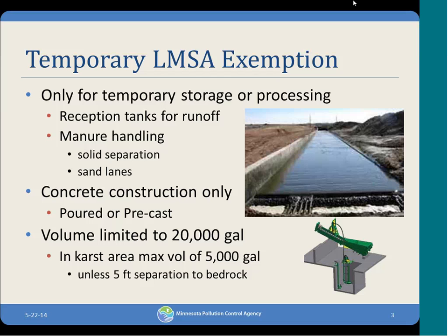Okay. Any other questions for Allie right now? All right, so one question is, how many days after the floor pour can it be walked on to inspect? Next day? Yeah, you can get on it the next day. You want to see how it's curing. If you see that there's kind of a slick on top, use your best professional judgment, but it should be fine the next day.